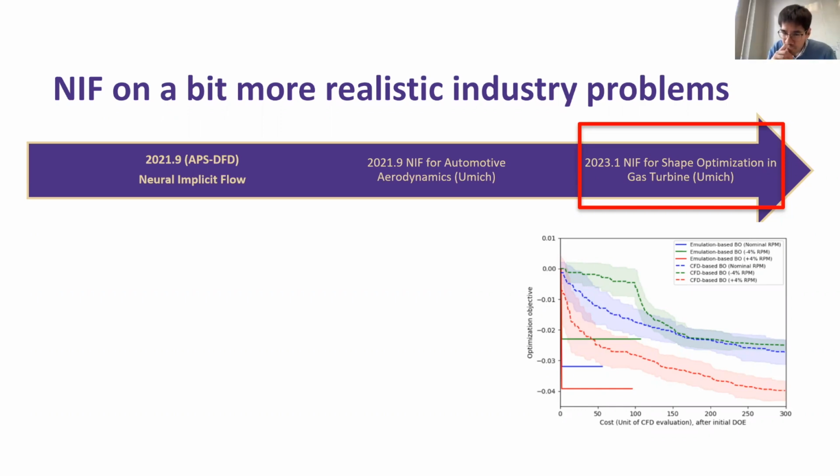Because the other question I had in mind is whether the cost objective is a quantity that's associated with the shape of the airfoil itself. Let's say it's a drag that you have to compute along whatever the predicted optimal shape is. Then over the course of the optimization, how do you handle the fact that this boundary is at an unknown location, since the NIF framework itself does not really have a notion of specific nodes in space?